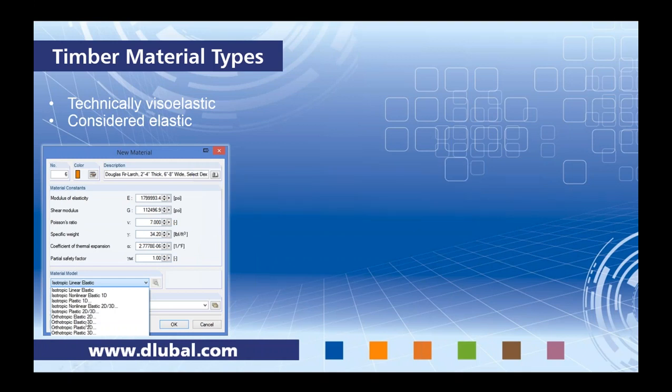All material models are listed here available in RFEM, and technically timber is considered viscoelastic, meaning that the strain rate is dependent on time. But realistically, we can't model viscoelastic in software. It's just very complex. So we will just go ahead and consider it elastic. This is basic behavior of modeling of timber.